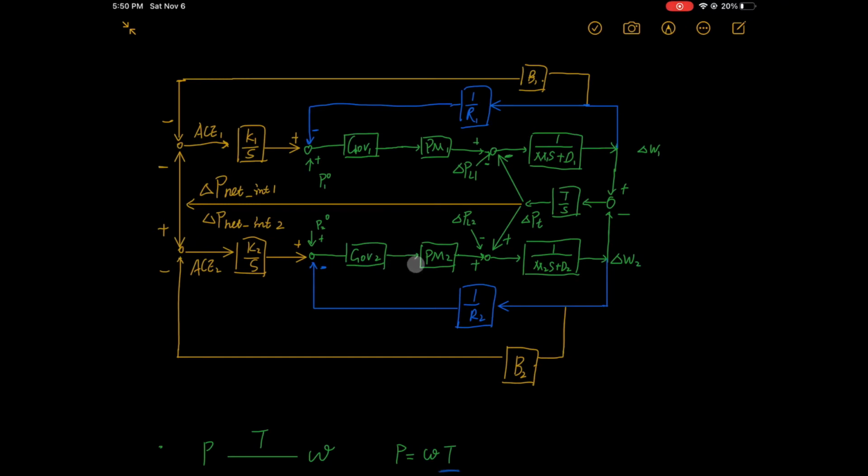Then how does the governor control the valve in an isolated generator? The idea is that if the rotating speed is higher than expected, then we turn our valve down a notch to let in less steam. We compare our omega with an omega reference and pass that difference to an actuator, including an augmentation block and an integral block. Notice that the speed governor tries to maintain the reference speed regardless of the electrical load.